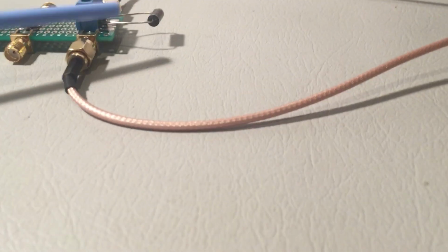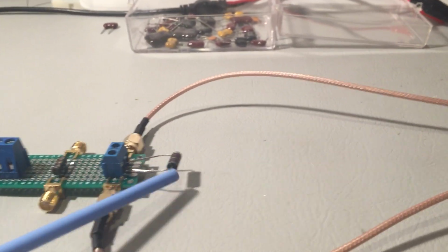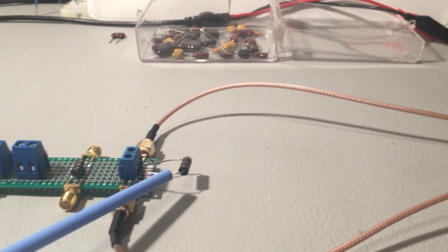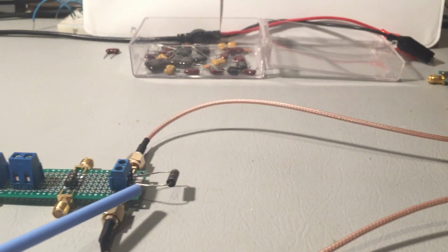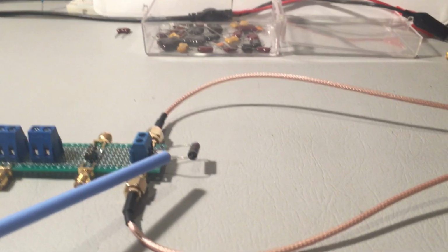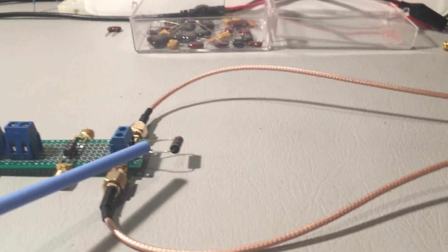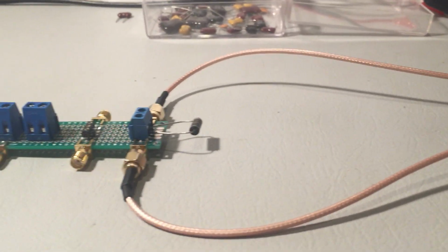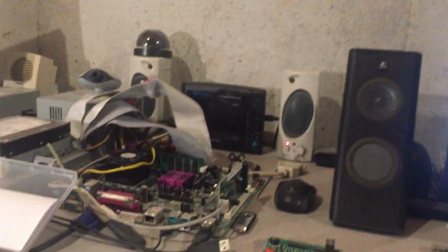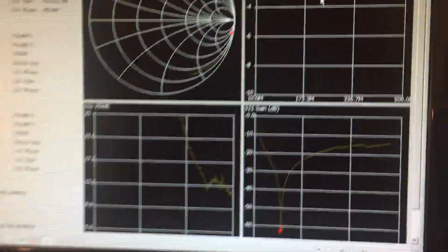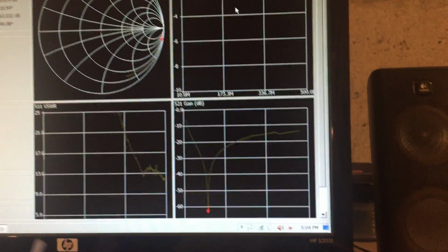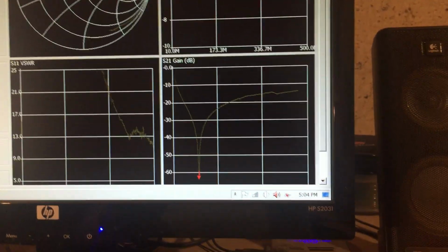But let me point out, I did a little bit of investigation to see what standard they use, and they are using components with shorter lead lengths in their test methodology. So we'll probably get a little bit different results, as you've seen previously, because I've got the full lead length of this inductor. So we're going to go ahead and sweep this. And again, I'm sweeping from 10 megahertz to 500 megahertz. I haven't changed that.